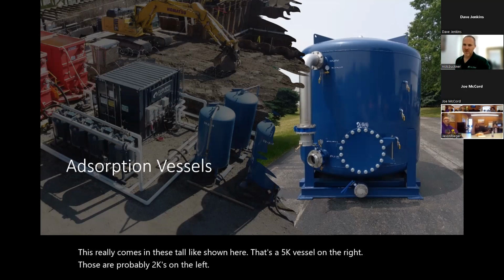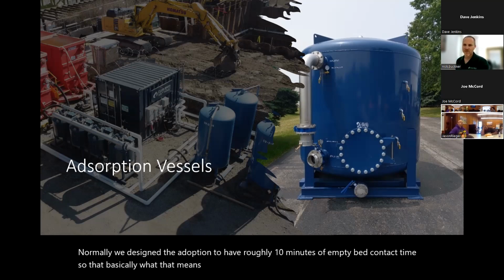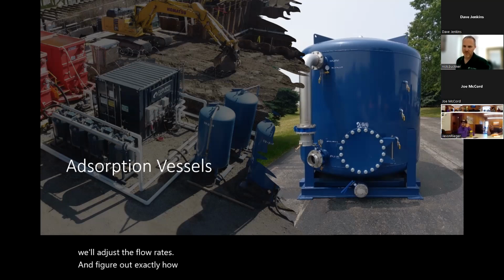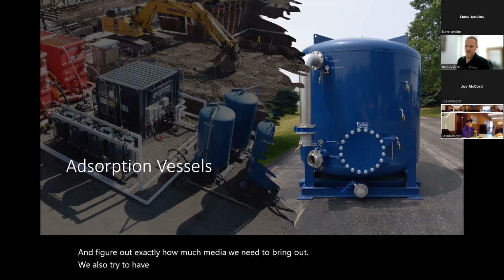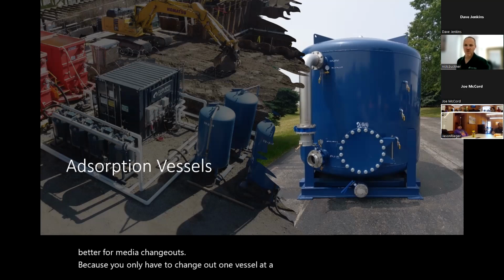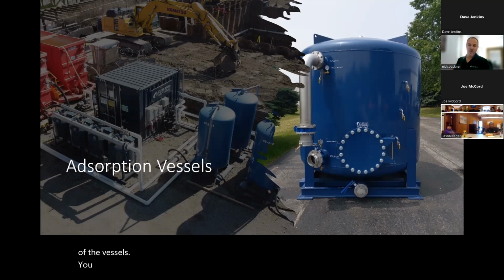Normally we design the adsorption to have roughly 10 minutes of empty bed contact time. So basically what that means is every drop of water will hit this media for 10 minutes. So we'll adjust the flow rates and figure out exactly how much media we need. We also try to have a duplex system so that we can establish lead lag vessels. This works better for media change outs because you only have to change out one vessel at a time, and you can switch the orientation of the vessels to compensate for the overall loading.